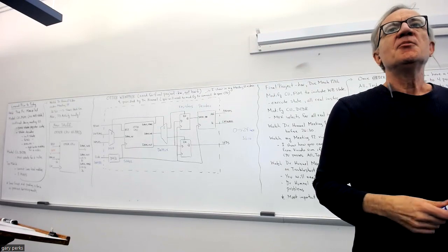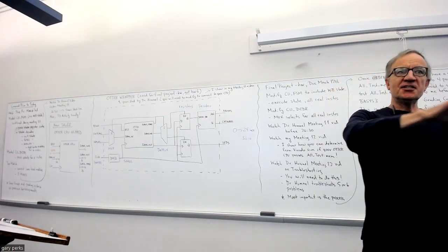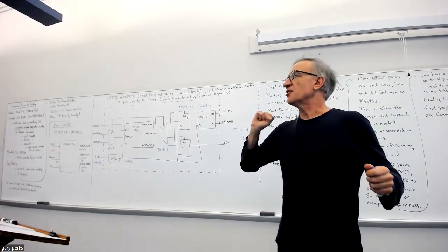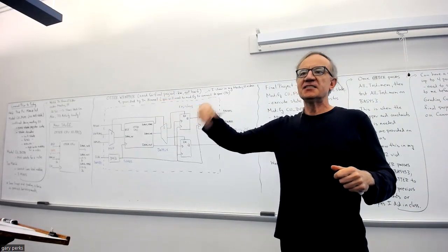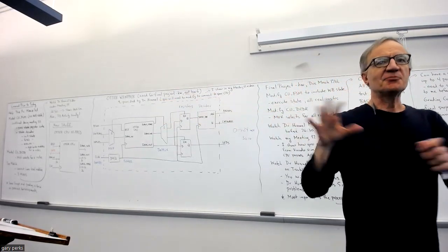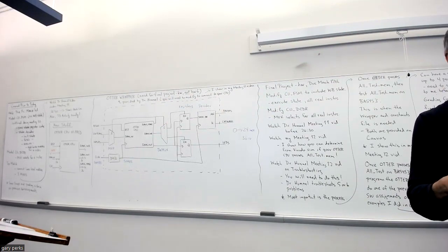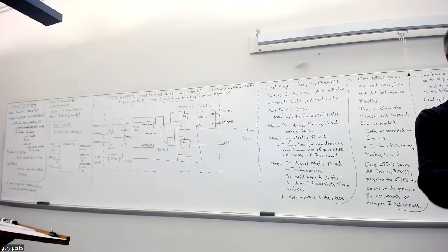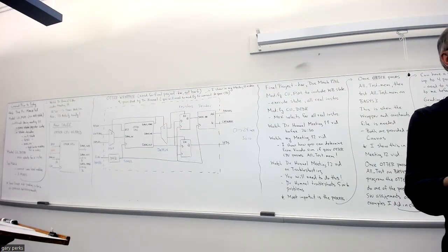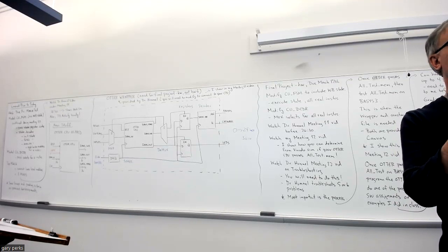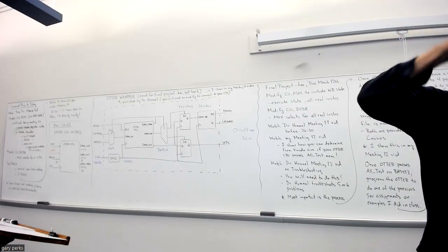So anyway, if you're dealing with switches, or if you're outputting to the same device periodically, you're going to have to put in a delay. But everything else, if your program was working in RARS without that delay, should still be working. And provided you do the delay correctly, it should all stay working. But again, you can test it in RARS.